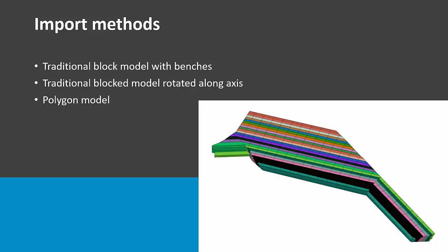we take those models on those planes. If you have several areas, we would do this independently. You actually flip the entire thing on its side. So I now have strips oriented vertically in a stack that Scheduler then progresses through as though they were benches. This can greatly speed up the solve time while also reducing the precedence that you need. You can do that for multiple panels. It still has the ability to do all the blending, all the sequencing choices, all the CapEx, all that's still in there. The third option is the Polygon model.